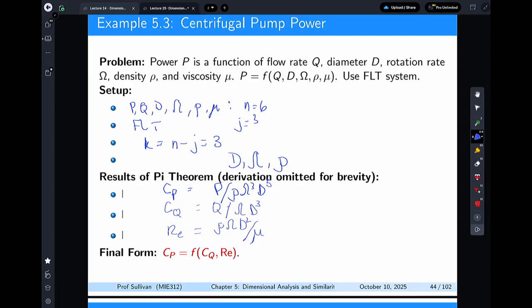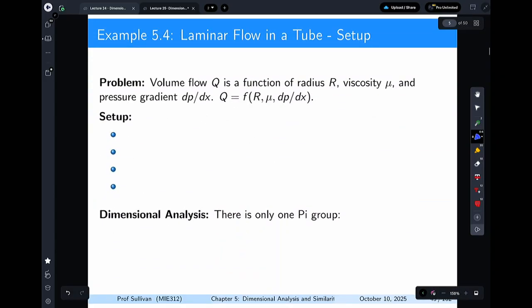Reynolds number, same sort of thing. I've got here a different form of it, but it basically is velocity times diameter times rho divided by mu. So it is a Reynolds number in the same sense. It's just going to take a different form because I have a volumetric flow rate associated with it, not a velocity. I could set this up and write it out as velocity and mass flow, but why? It works the same way.